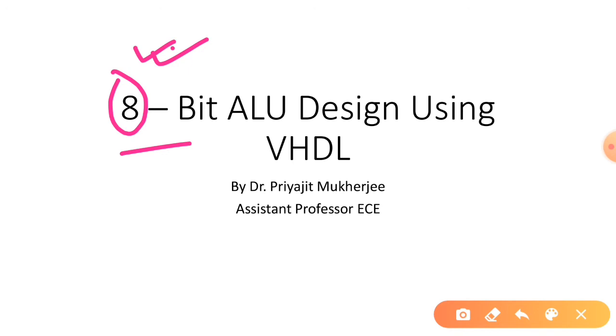If it can perform this on 16-bit operands, then we will call it a 16-bit ALU. If it is a 32-bit operand, then a 32-bit ALU. 64-bit, then a 64-bit ALU. So in this particular lecture, we will be studying the designing of an 8-bit ALU. It has two 8-bit operands on which it will perform different arithmetic and logical operations.